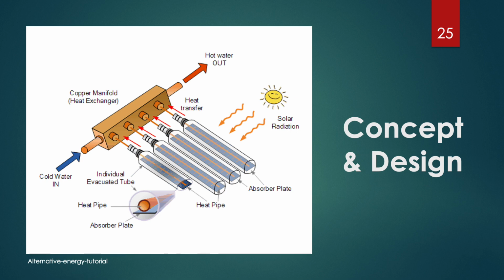manifold within the header tank. These copper pipes are all connected to a common manifold, which is then connected to a storage tank, thus heating the hot water during the day. The hot water can then be used at night or the next day due to the insulating properties of the tank.